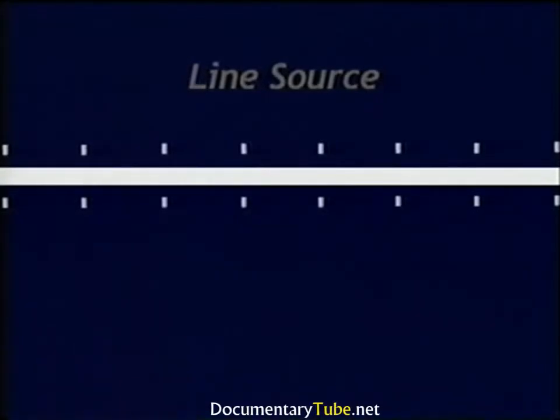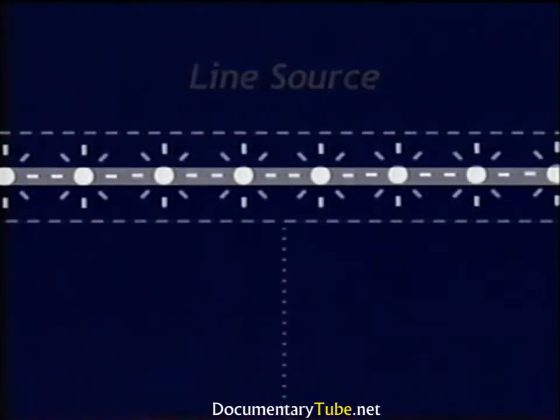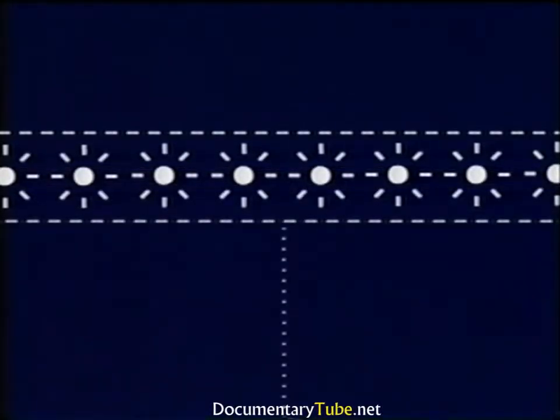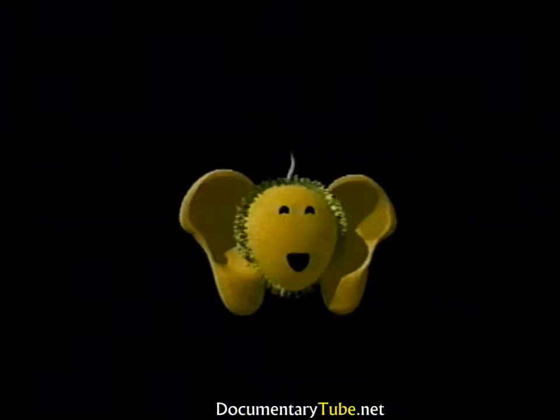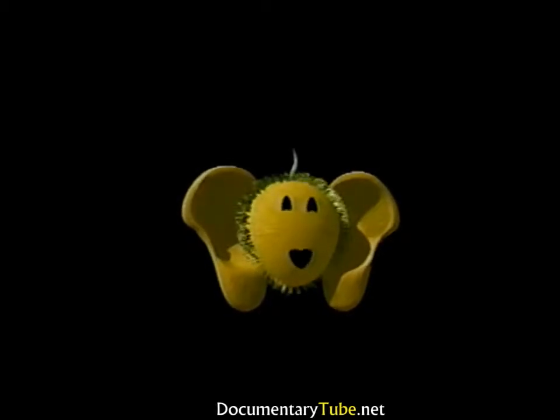A line source radiates sound cylindrically. It can be composed of multiple point sources arranged on a line located at a perpendicular distance relative to the observer. The sound levels measured from a line source decrease at a rate of 3 dB per doubling of distance. This is a decrease due to cylindrical spreading. 2 theoretical sound source types have been described.